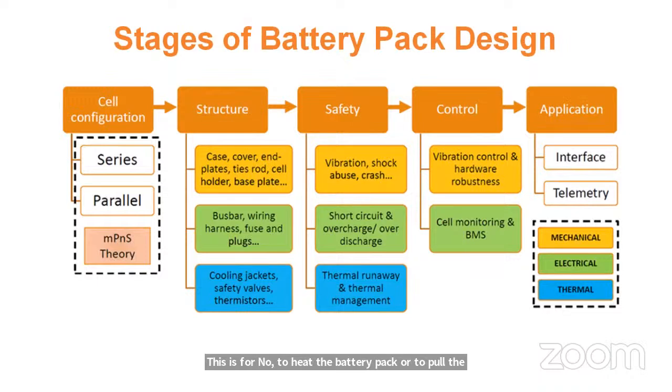See, thermal management of the battery pack is required, because these batteries are very sensitive to heat and so on. So for that we do this thermal management. Otherwise, what will happen? Thermal runaway could happen. In the last 2-3 years in the news you might have read that this vehicle got fire, that vehicle got fire. The major reason behind that could be thermal management. So thermal management not only means cooling down the battery pack. Thermal management also talks about heating up the battery pack.